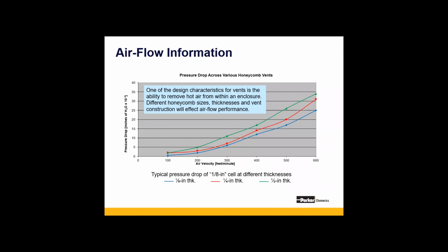Okay, and then there's a lot of aspects to the airflow itself, or called pressure drop, and the biggest, easiest to show is cell size versus thickness. So other aspects to note are plating, honeycomb angle, foil thickness. They all come into play. Protective grills or dust filters.